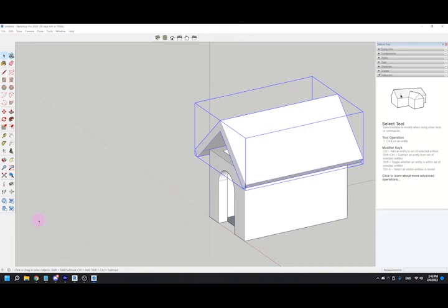But first, I'm actually going to undo. So let me Control Z, so that it's no longer a group. And I'm going to show you why I'm drawing my windows from left to right instead of right to left. If I started down here and drew this window, see how this has that dotted edge to it? If I release it, it also is going to include this. So this is what we call a window selection, and this is what we call a cross selection.